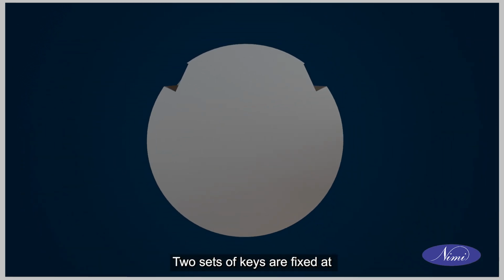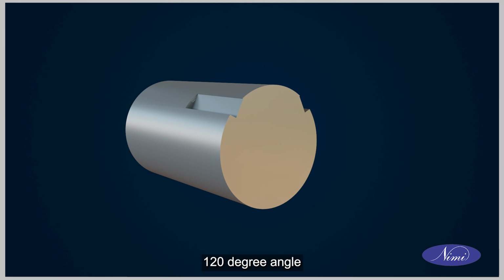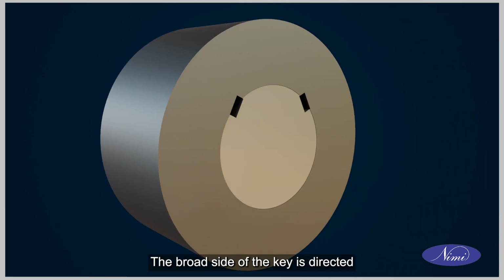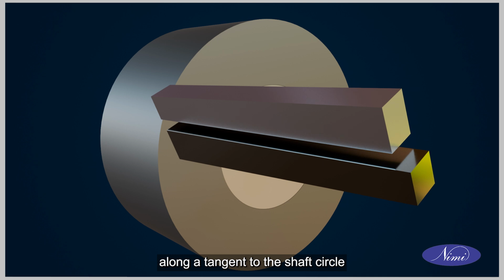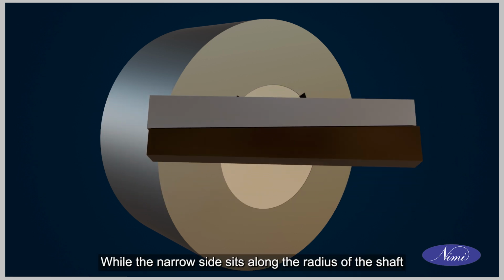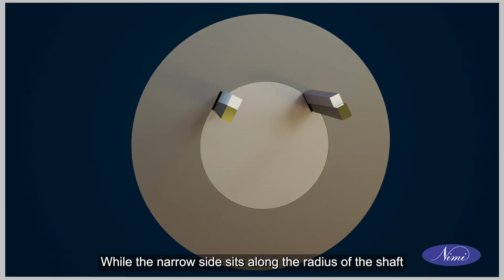Two sets of keys are fixed at 120-degree angle. The broad side of the key is directed along a tangent to the shaft circle, while the narrow side sits along the radius of the shaft.